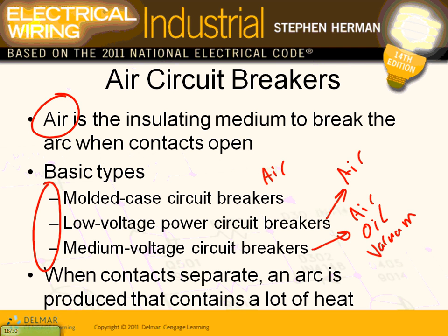The way they split them this way is based on the construction, how they build them. So molded case circuit breaker, you're looking at it right here. That's mostly thermomagnetic circuit breakers, like these. These guys, I believe they probably can do 1600 amp max. These power circuit breakers start making sense from 800 amp to 6000 amp.